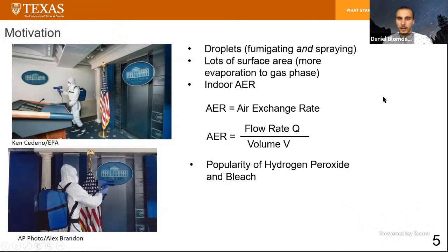A concept that I will familiarize you all with is called the air exchange rate. That is a trait of any indoor space, and it's defined as the flow rate over the volume, in units of volume per hour. A very large air exchange rate is a space that's flushed out and very well ventilated, while a very low air exchange rate is one where the air is very stagnant, and anything that's emitted into the room, the concentrations from that will stay elevated for a long time.